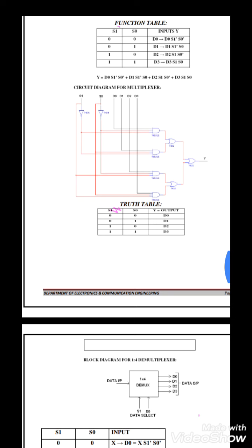There we give the data 0. For that time the output is also 0. And there we give the value 1. For that time the output is also 1. So the output Y always depends upon our D0 input. So that is the first combination of inputs.